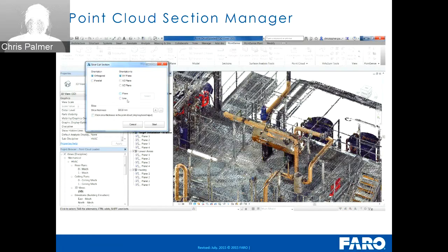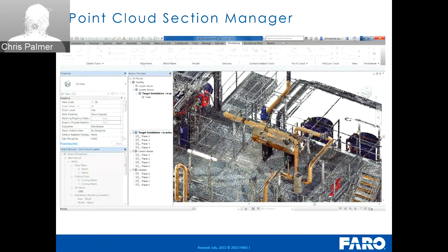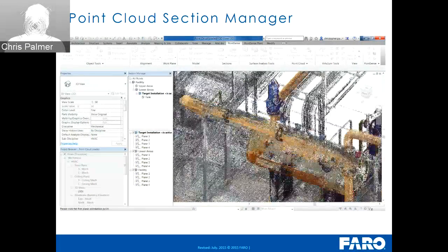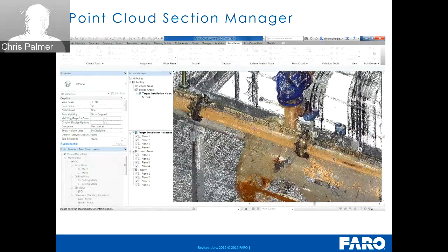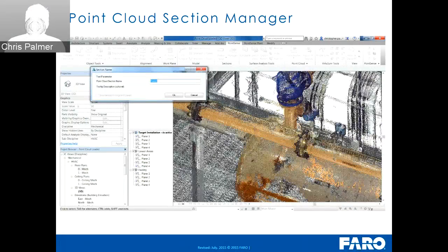But if we maybe go for a 500mm slice, orthogonal to the X and Y plane, and we just zoom in on a specific pipe here, I literally just need to give this 1 click, and that's going to define a plane orthogonal to the X and Y. So we'll call this, just for reference, orthogonal 500mm slice, and we should probably say against the XY, so 2XY.